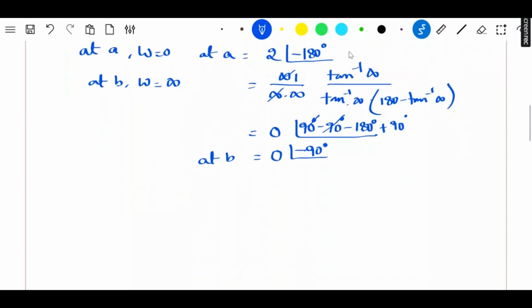And if I take these two values and try to draw the trace of the linear contour, I'll be able to see that the magnitude at A equals 2, but the angle is minus 180, and angle minus 180 will come this side. Okay, angle minus 180 is this. And let me take, this is the point where the distance is 2 at an angle minus 180. And this point is actually A dash. Now when I go with 0 magnitude, it means it is at the origin.